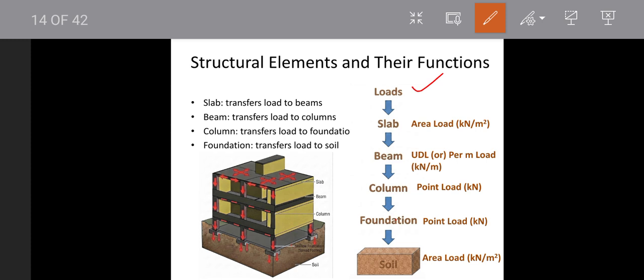If you see in this figure, the load is first acting on the slab, from the slab it is transferred to the beam, from the beam to the column, from the column to the footing, and from the footing to the lower soil area.